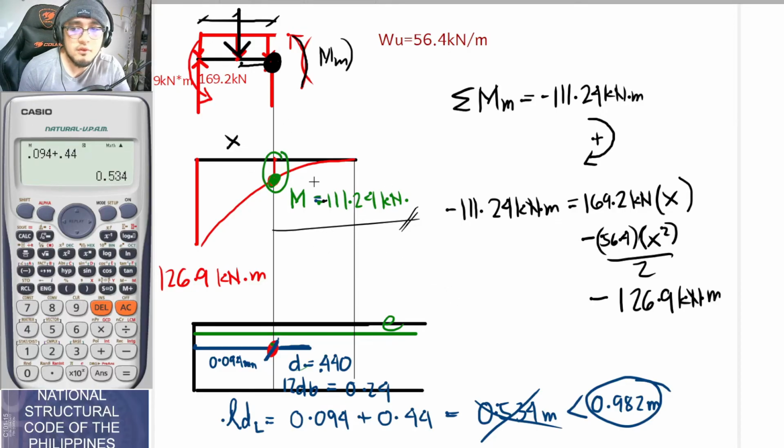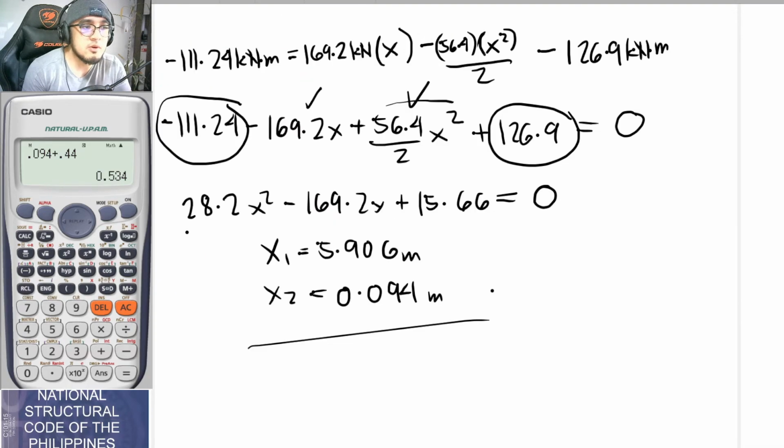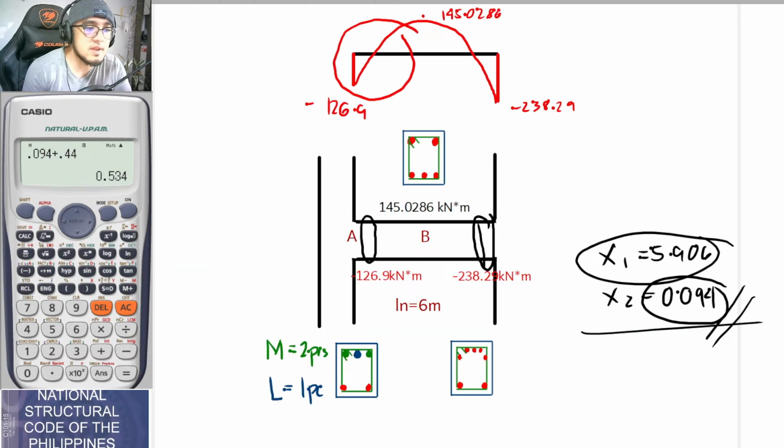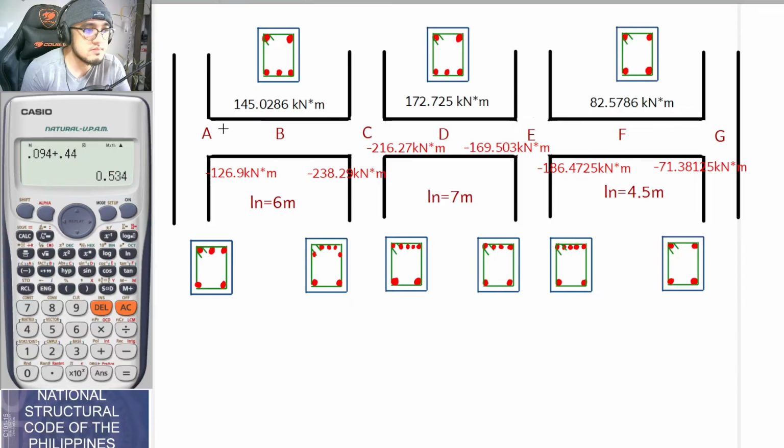But what about for your bars M? In actuality, guys, if this is to be your section, this is to be for your bars L, and this is to be for your bars M. In actual construction practices and according to the requirement in SMRF, you must provide 2 rebars at the top and 2 rebars at the bottom throughout.